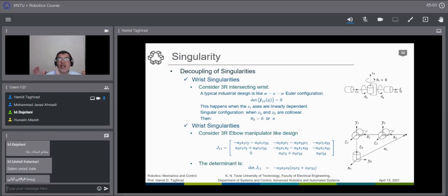dependent on each other, or these lines become collinear, if these 3 vectors become parallel or lie on one line, the matrix formed from these 3 vectors will be singular. We can see that if these 3 vectors, or these 3 screw axes, become collinear, then we have a singular configuration.